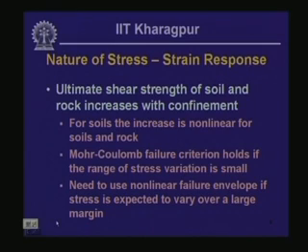So now we are in a position to look at the major features of the stress strain response. What we have seen is that the ultimate shear strength of soil and rock increases with the increase of mean normal stress, or increase in confinement.